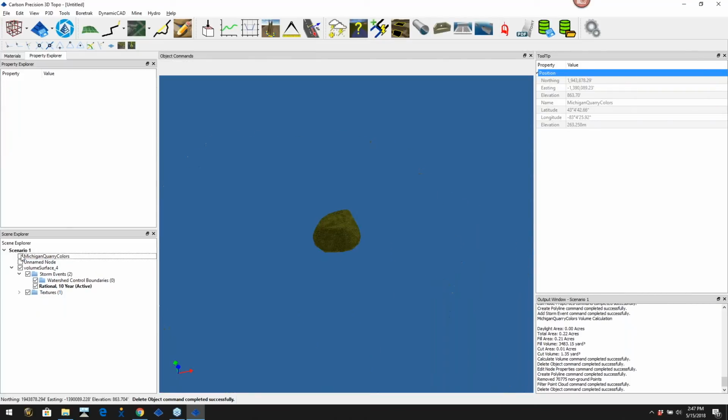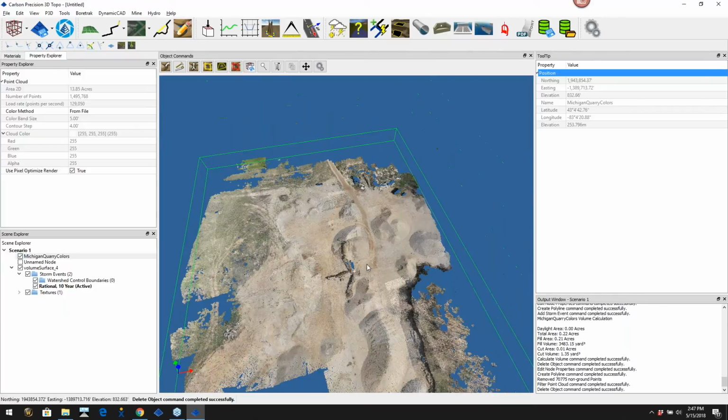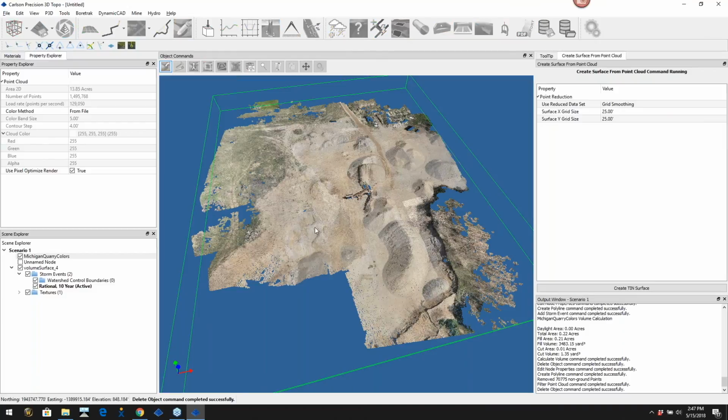So you can not only do your drone survey, but if you pick up some important points or break lines, you can also bring those into P3D Topo after you process the aerial drone photogrammetric cloud, and then you can augment and increase the accuracy of your surface model in P3D very quickly and simply. And then you right-click on it, save it, export it as a Carlson TIN or LandXML file, take it back into your CAD software of choice, and create your contour maps or finished reports.